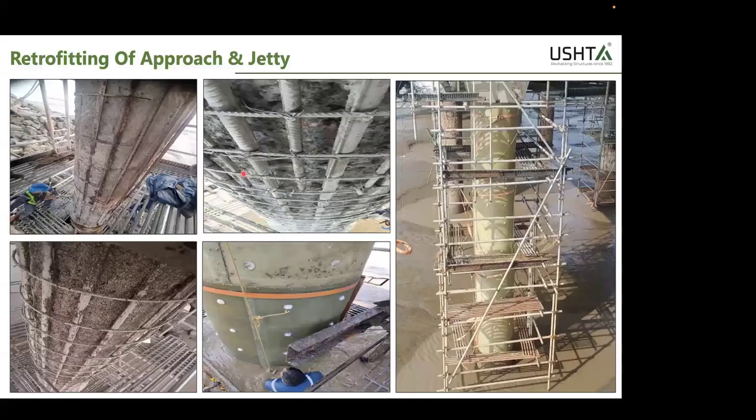And finally, above water, we built up this section with micro concrete. All these materials were moisture insensitive materials, because if you see the data sheet of a regular material, they'll mention that moisture level should be less than 4%, whereas in a jetty it is never so. It is 100% saturated, and the moisture levels are more than 90%.